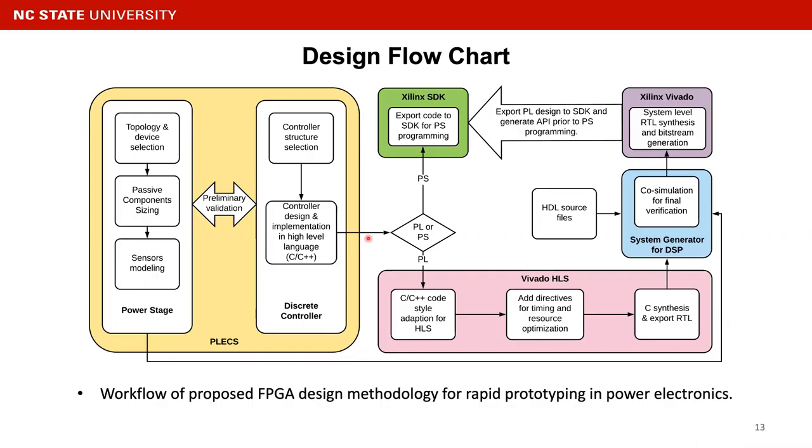The next step is to try to implement the control algorithm in the actual controller hardware. So for this Zynq 7000 SoC platform, the very first decision we need to make is whether we want to implement a particular algorithm in the PS or PL. If we want to implement some algorithm or controller in the PS part, that would be easy because we already have a working prototype C code from the simulation.